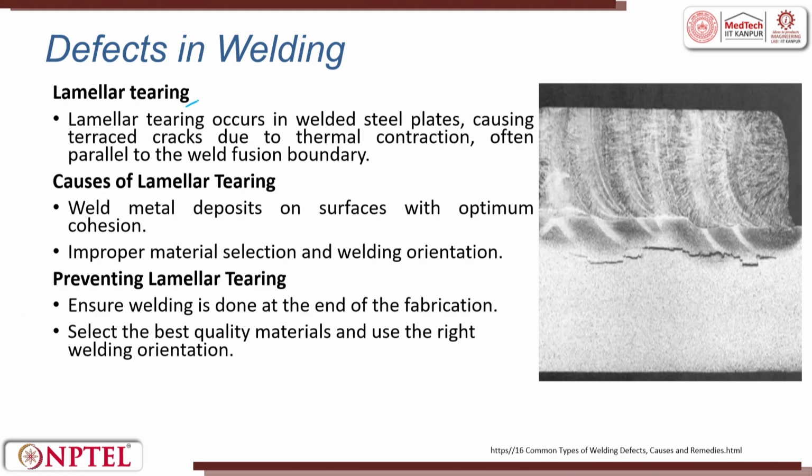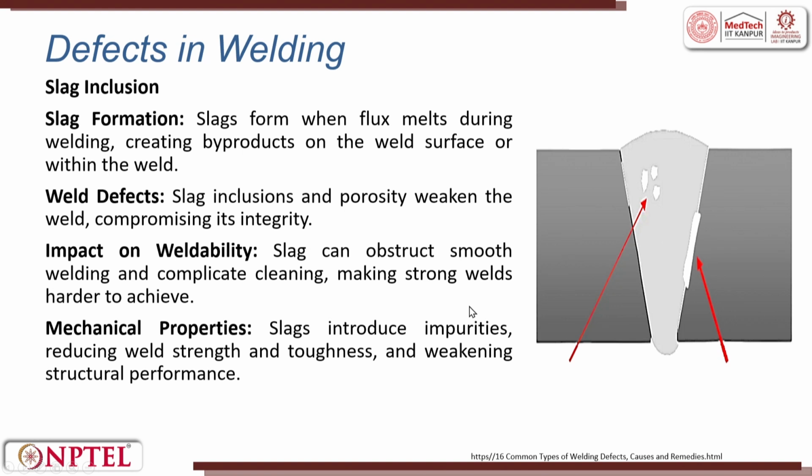Then there is lamellar tearing. Lamellar tearing occurs in welded steel plates, causing terraced cracks due to thermal contraction, often parallel to the weld fusion boundary. This can be prevented by ensuring welding is done at the end of the fabrication. You try to do it because thermal contraction plays a very important role.